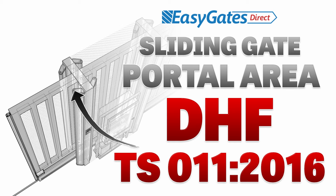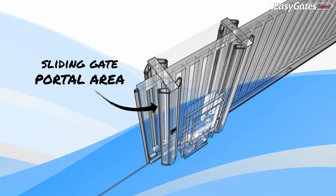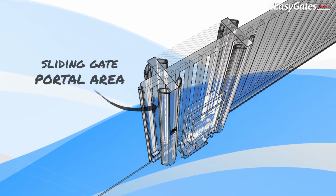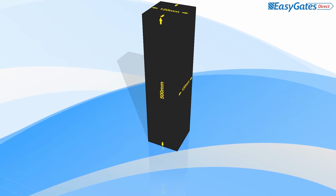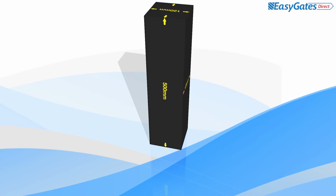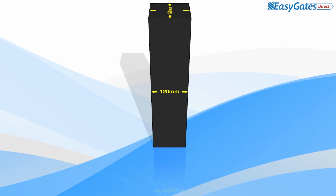Chapter 4. Performing safety tests in the sliding gate portal area. In the following animations, we will explain in simple terms how to carry out these tests in line with the Code of Practice. Firstly, you will require a compliant test piece as illustrated on screen. This must meet the dimensions specified of 120 by 120 mm in diameter and 500 mm in length. It must also be made of rigid material such as steel or hard polycarbonate.